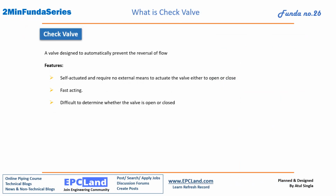So a check valve is designed to automatically prevent the reversal of flow. When we want to allow the flow in a single particular direction, only then are these valves useful. These are self-actuated and require no external means to actuate the valves. There is no handle, no stem, no body for stem holding. So these are very simple to construct and are very fast acting valves. It is difficult to determine whether the valve is open or closed, because we don't have any rotating handle externally, so that we know whether we have to close it or open it. These are all self-actuated valves.